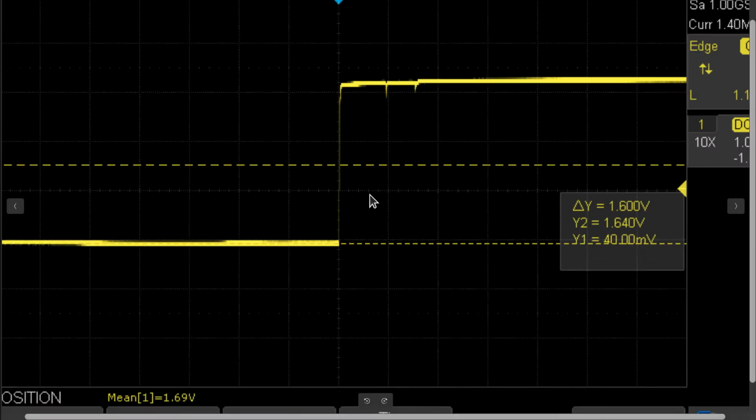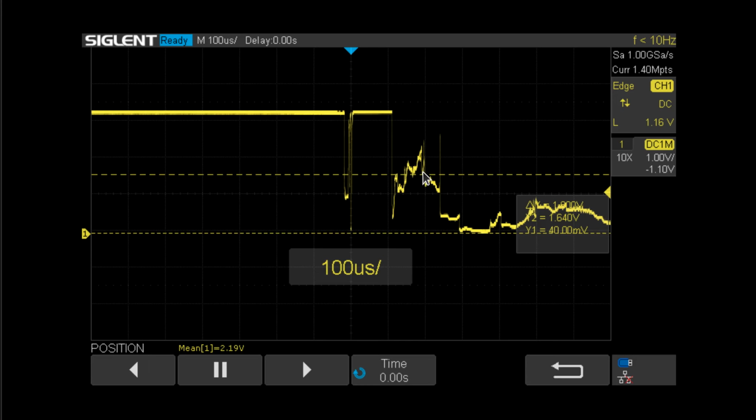Here's a really nasty looking one. This is one situation that could cause some serious metastability in your circuit, okay, by it literally being in the middle, so you don't know if it's a 1 or a 0, and the clock is going to tick a bunch of times. It may very well be that this could go metastable. And this is why we do a synchronization in our circuit.